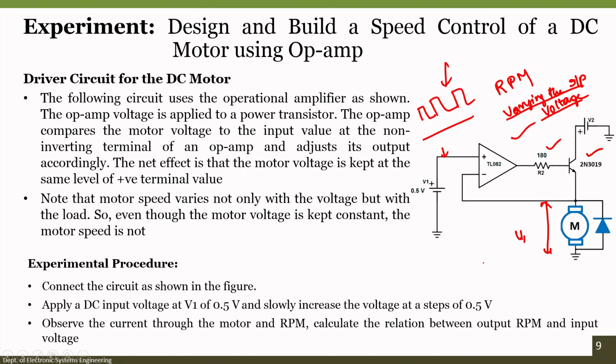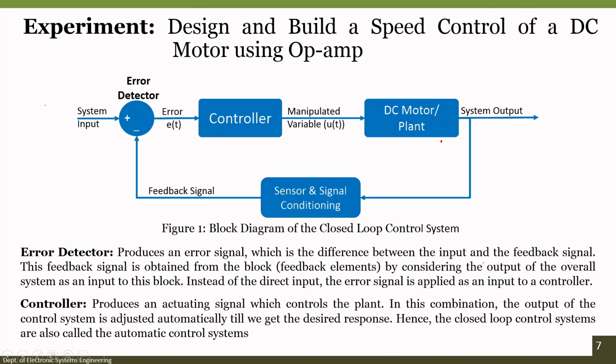With this understanding we will go with the same sensitivity factor of 20 RPM per 1 volt. The system will not understand whether 1 volt is 20 RPM or 100 RPM, but this is only for our reference. What the system tries to understand is whether the feedback signal is also 1 volt or not.